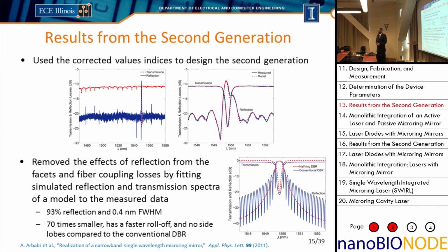figure out what's going on in our device geometry and our device parameters from observations of the resonances of the ring. The reason that this method is very accurate is because we can determine the resonant wavelength of the ring to on the order of 1 picometer in a measurement that has 1550 nanometers. So it's essentially about 6 or 7 digits of precision that we can measure these resonance wavelengths, lambda. So then the question is, how precisely can we model the structures? And it turns out that we can extract several digits of precision in our parameters, both for the parameters at room temperature and also their dependency on temperature.